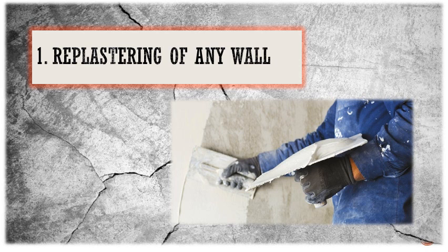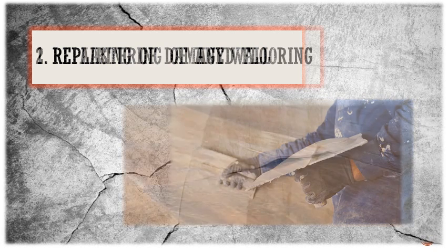Patching a plastered wall is a great deal easier than replastering it from scratch, but often the job that needs to be done needs more extensive work. Because if the patches are large or extensive, it simply isn't worth doing. If you have hacked the plaster off half a wall, it will probably be better to replaster the whole of it rather than simply making good the damaged area.